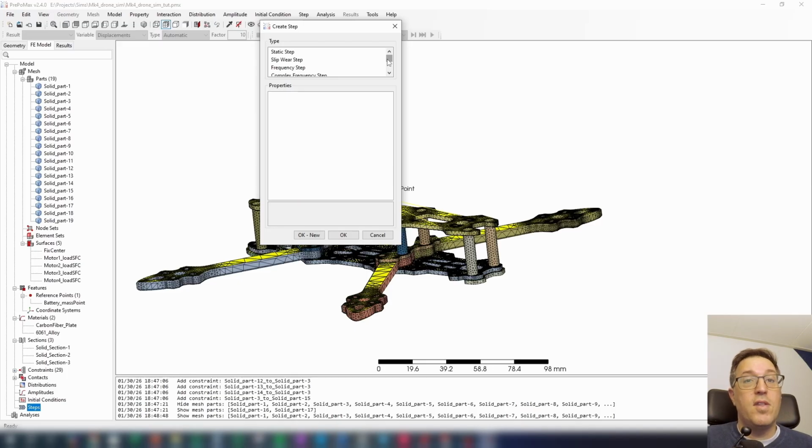It's where the profile of the impact falls under one of the natural frequencies or the dominant frequencies of the system. This is where it doesn't really represent real life, because we're amplifying that impact just because it falls under the resonating frequency of the system.